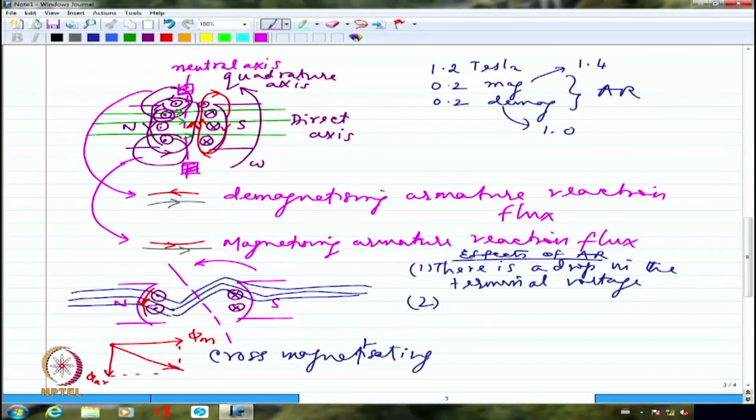It is going to say, I will carry the current for some more time, no matter what. So it is going to carry the current for some more time under heavy opposition from the main poles. And that will essentially spill over into the surrounding air. There will be a larger voltage induction. L dI by dt will manifest itself in the form of sparking that occurs in the DC machine. Right? That is why the sparking increases whenever there is a higher armature current. The sparking will increase when there is a higher speed as well.